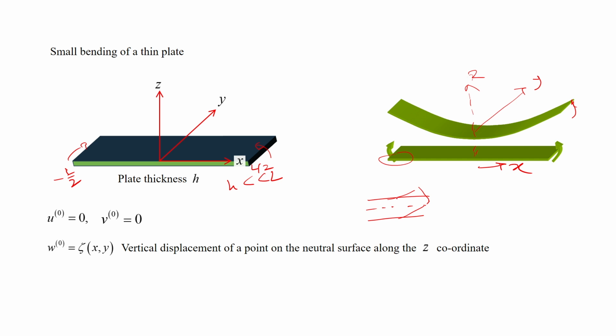So in this region, the inner side, this surface becomes compressed, and the outer surface becomes stretched. So there is a compressive load over here and a tensile load over here, and that becomes 0 at the neutral axis. At the neutral plane, there is no tension, no compression. So this is called the neutral plane, not axis, neutral plane.